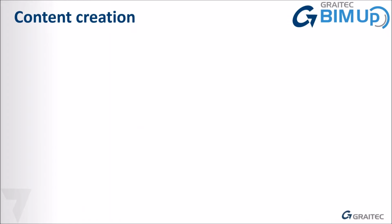Okay, we'll have a quick look at content creation, because if you're transferring between Advanced Steel and Revit, a lot of the modular buildings use C channels that might be fabricated in your own workshop or bought from a supplier, and they're not standard hot rolled members. So with your Revit structural family creation, it's really important that you create this content properly. Otherwise, when importing and exporting, members just come in the wrong way, and the position isn't correct.